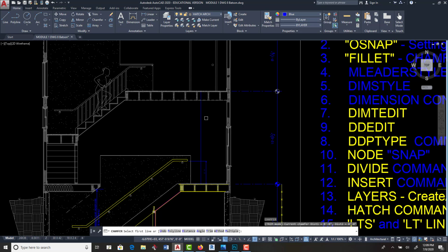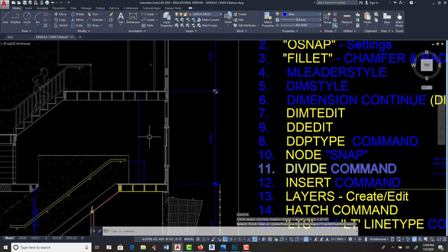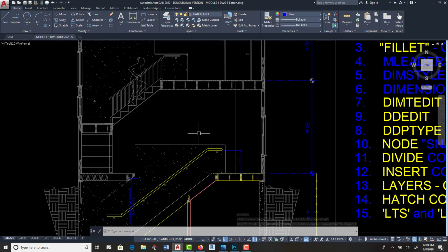Okay, I can't use 24, so I'm going to try another number. You're going to try a bunch of numbers, and then you're going to use your divide command. Let me try that one more time. Clear. 128.5 divided by, let's say, 22 risers. Enter, equal. Can't use that, so I'm going the wrong way.